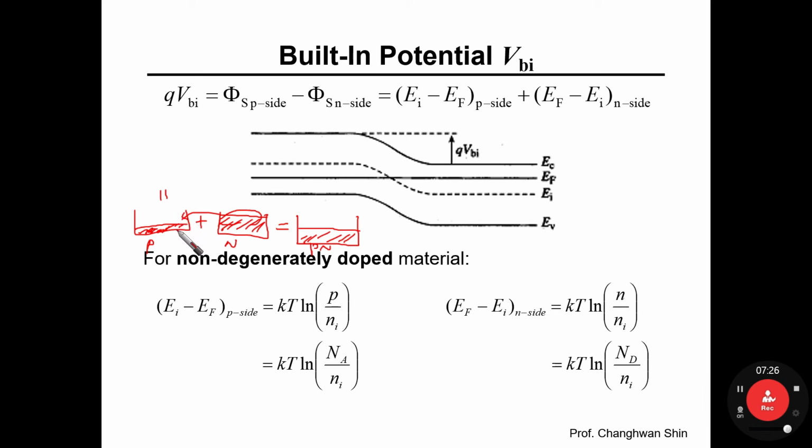Okay. And then what kind of physical or natural forces would be engaged in this PN junction? Yes, this built-in potential. So with your knowledge, let's draw the band diagram. That would be the easiest way to catch how the PN junctions are formed and how the built-in potential has been set up.